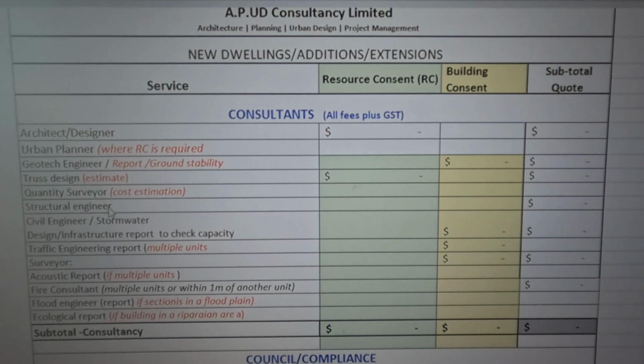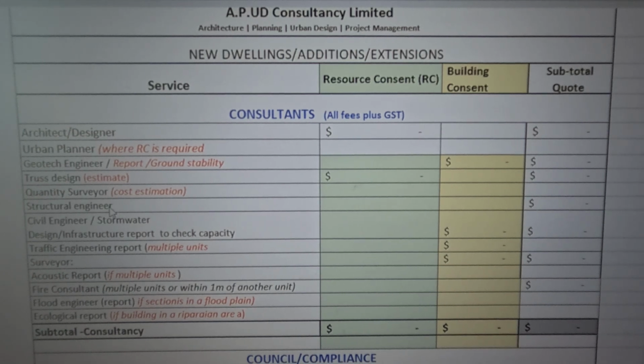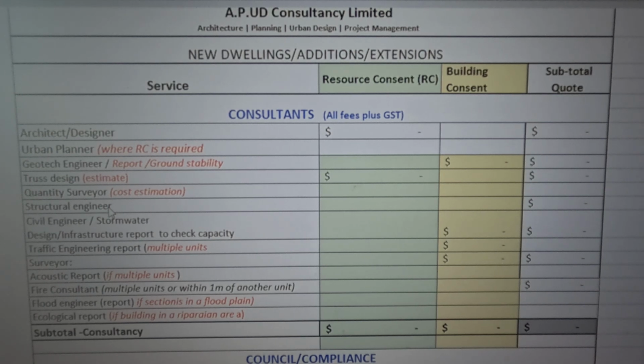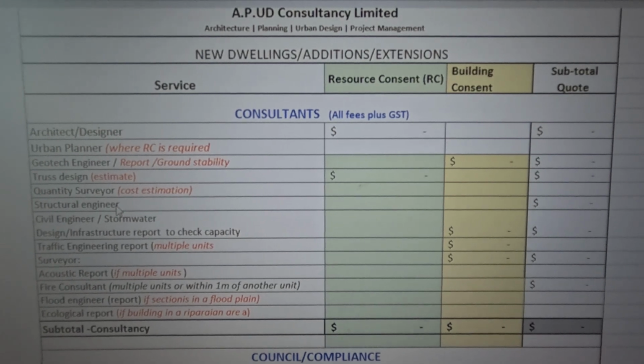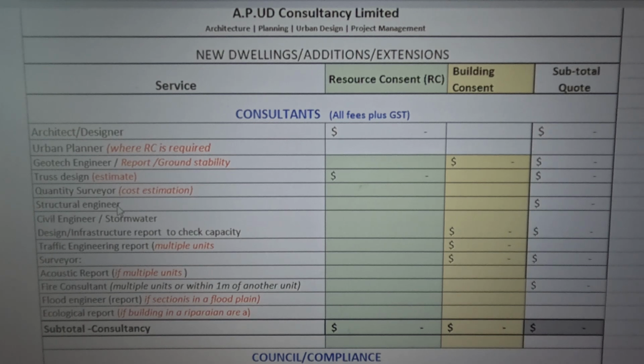Now, if the geotech engineer recommends that your foundations need to be specifically designed, then you're definitely going to need a qualified structural engineer to design those foundations, and also do your bracing. Although sometimes, for a small or straightforward building, your designer can do the bracing straight out of 3604.